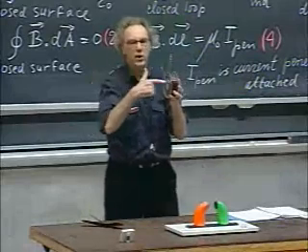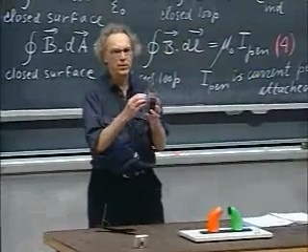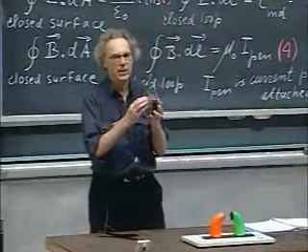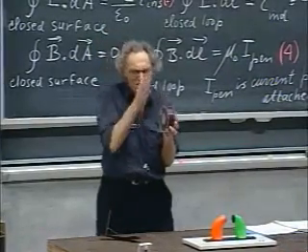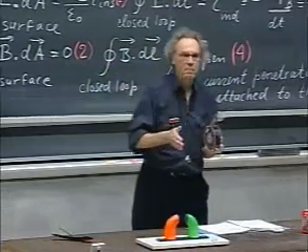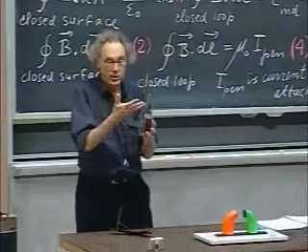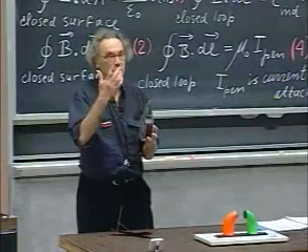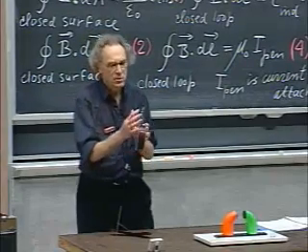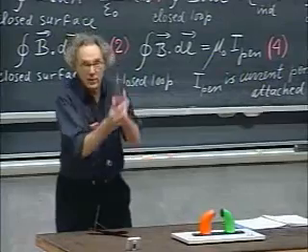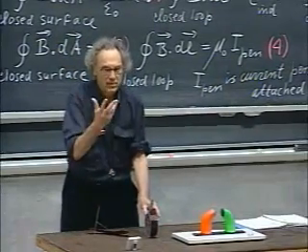And when I move this between these poles, magnetic field, let's say, is going in this direction. I don't know whether it's in this or that. I don't know the color code. But there is a magnetic field going through here. So there's a change in the magnetic flux through this surface. Very crazy surface. If there are 1,000 wires, this surface goes 1,000 times like this, remember? And then there is going to be an induced EMF, and an induced current. And this light will glow a little. If I go in very slowly, you'll just see a teeny weeny little light. If I go very fast, then the magnetic flux change is high. High EMF, a lot of light.